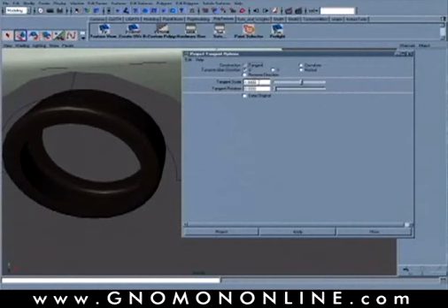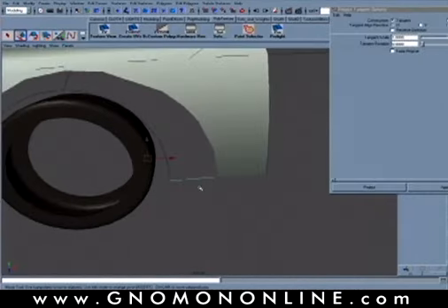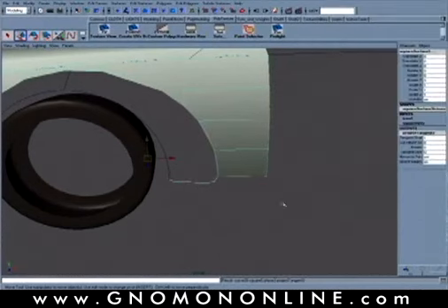Most of this stuff you can change afterwards, so it's not a big deal, other than you may want to keep originals off, and then proceed from there and change this later in the attributes. So the way I'm going to set up my project tangent is you'll select your curve, shift select the surface, and then say project.